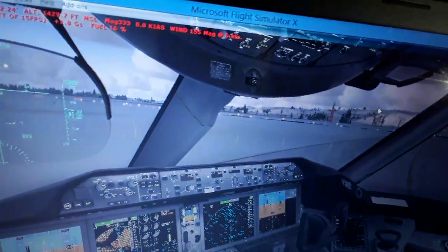In the Airbus you have left and right turns limited to 2.8 G or 67 degrees, and also you have climb 30 degrees or 1.5 G's, and descend minus half G's or minus 15 degrees.